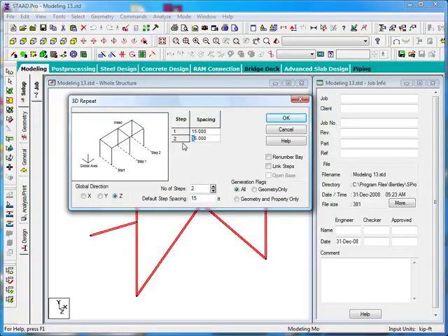It's also good to note at this point that the spacing values take on that default value, but there's nothing that prevents us from coming in and overriding those values if we wanted different spacings for the different steps. In this case, I actually want both of my spacings to be 15, so I'll just come back to a value of 15 for each one.